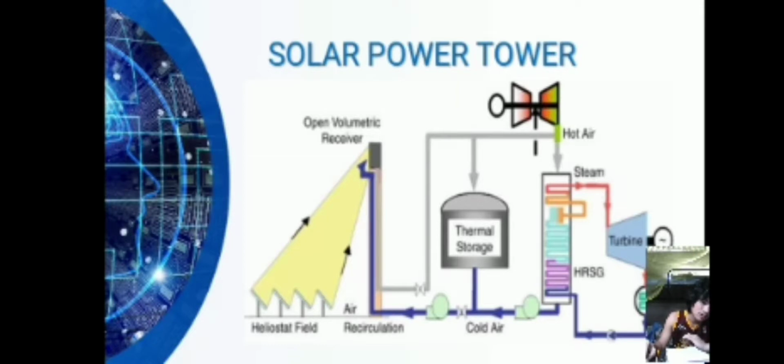Then in the heat exchanger, the heat of the HTF is being transferred to the water, making super hot steam. Then that steam go to the turbine, then producing electricity. Then again, the superheated steam being condensed, then goes back to the heat exchanger. So, ganun lang siya, guys.